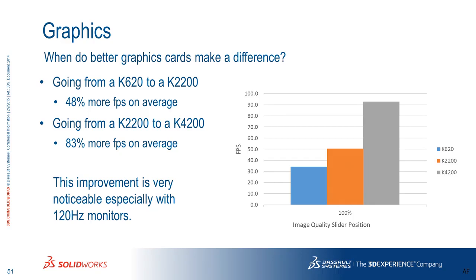Now, small assemblies, single parts, all of this is where you're going to see this kind of improvement. But does anyone here think that they have a model that requires that level of tessellation to view it comfortably? Because this kind of goes against everything that I do, which is modeling methodology. And I will tell you time and time again to stay out of the red zone, stay out of that 100% zone. And if you're going to do what we ask you to do in modeling methodology and stay out of that zone, then you have to build that kind of tessellation into your model naturally. And I can't think of a situation where that would occur.